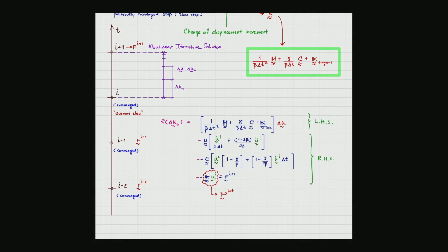That's a lot of things that is going to take a lot of your computer resources. Well, the time stepping size could be bigger than in explicit time integration due to the stability of the scheme. The implicit time integration allows you to use a bigger step size.